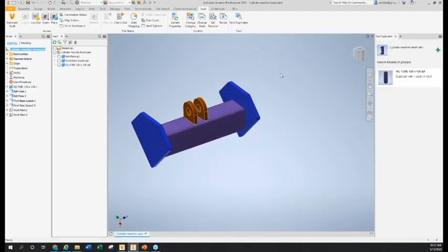We just go search, and it identified one part here. If I hover over that, notice it shows that there is already another part out there called square tube 120. So that's the one I'm actually looking at. It shows this is the one that found a duplicate. If I click on that, it searches the Vault, and it found that there's another part number. This looks like it's got a generated part number, 10005, and this currently has the same geometry.